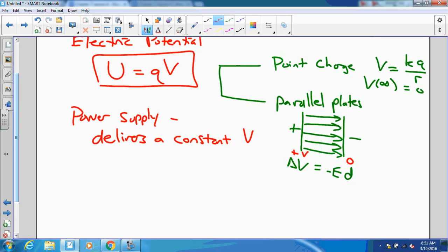An analog voltmeter, like any analog instrument, is going to use the position of some needle to tell me how much I've got here. And because we have to measure in the wild a large number of different ranges of voltage, there are going to be several different scales. And you're going to read these scales according to the number that you have here. The numbers on the scale are 10, 50, and 250 for the max. So if I'm reading 10, 25, 50, 250, or 500 volts, I'm going to go to the appropriately numbered scale and possibly multiply by 10.